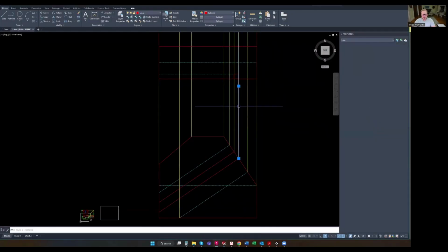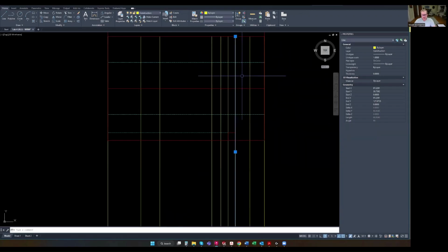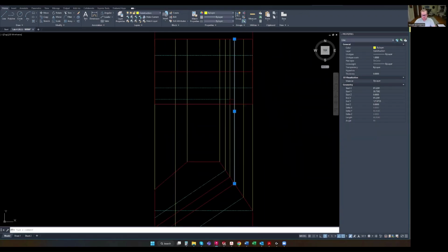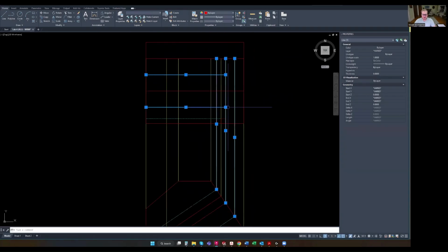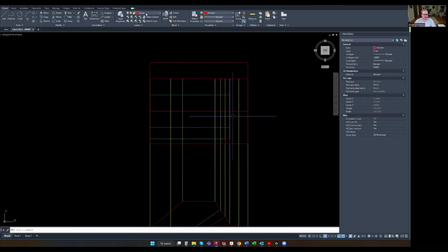But knowing that that's where it is, we have the information for the top and the bottom of our slot. We have the hidden lines here and here. What we can actually do is back those hidden lines down. Just select the pick point at the end, back them down to where the center point is. And then with our holes layer active, grab our ellipse tool, which is right here. If it's not the first one, if you have one of these other ones here, it's the center ellipse that you want to use. Go ahead and grab that.